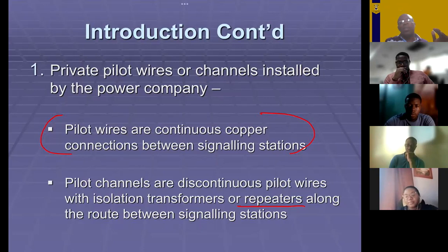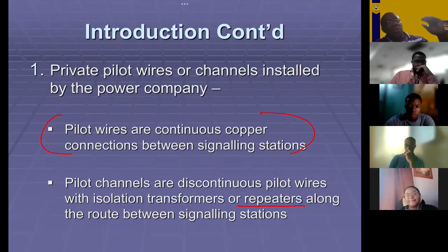If you then see something coming to you which was, say, below, I don't remember what the threshold was at the bottom end, but let us say it was now at 1 volt, that will be reproduced as 0. So you get back your 1, 0, your ones and zeros, which you can then move on. Are we clear? So the repeater stations are looking for threshold values. So you have a high threshold, you have a low threshold.